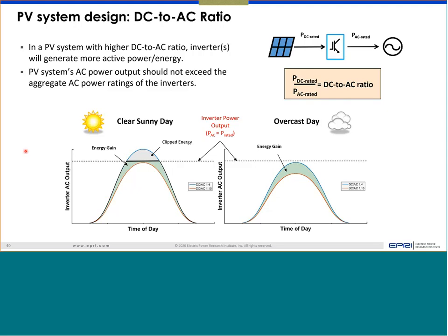Is there a reason to do this to offset dirty solar collectors? That could be another option. In a location like a desert type of environment, you have a lot of dust, maybe rather than doing a periodic cleaning, they will throw some extra panels to generate more DC. So those could all be reasons. As I mentioned, the reason is simple, but how they calculate whether it should be 1.5, 1.6, 1.8, what is the break-even, depends on a lot of factors.